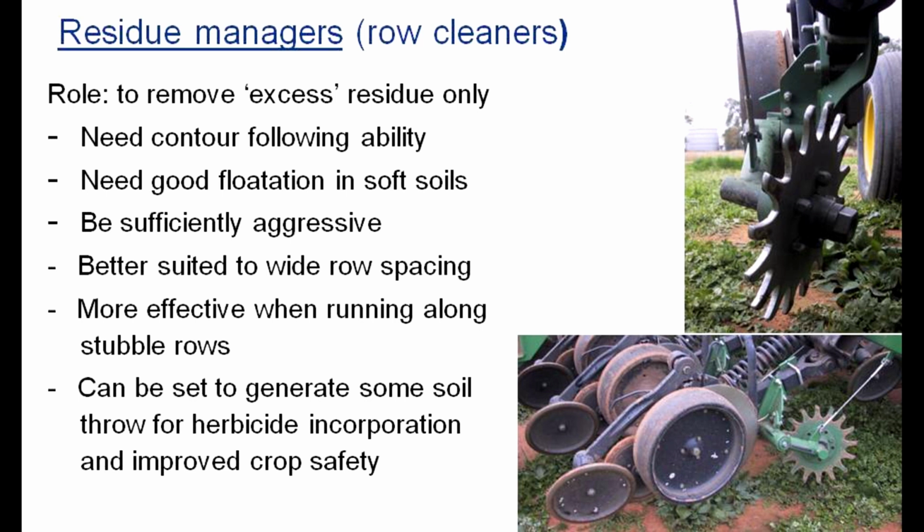Well, a lot of the disc seeders have side forces. The single disc seeders have side forces. A disc needs a lot of weight to do the job of penetration, so there's very little weight left on the wheels of the seeder, which typically act as a rudder. Essentially it's a stabilizing force. So these are the reasons why that happens.